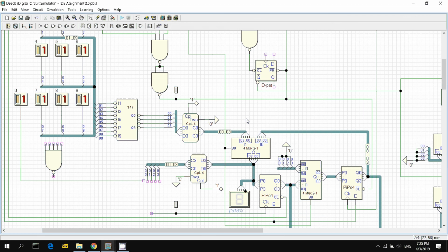Of course the delay in this part here is much higher, because you have to go through the priority encoder, and then go through the complement, go through the multiplexer, 3 things, of course it will take very long. Whereas this part here, you only go through the NAND gate, and then straight to the clock, so it's like no delay at all. So it's super fast, too fast that it becomes a liability, too fast until you cannot achieve what you want. So that's very annoying, but I think it's very good. I mean, it's more realistic.